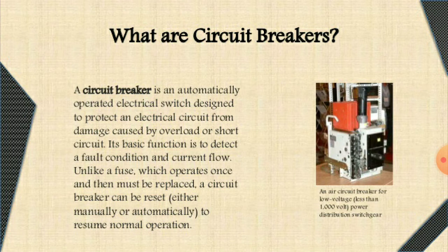So these protective devices, under that, the latest technology uses circuit breaker as the most important and commonly used protective device. Why? Because this acts as an electrical switch which will be in the on position under the normal condition. When a fault occurs, it will disconnect the fault circuit from the healthy circuit. So here we can define the circuit breaker as the electrical switch which is used to protect the electrical circuit from any kind of faults like overload or short circuit.